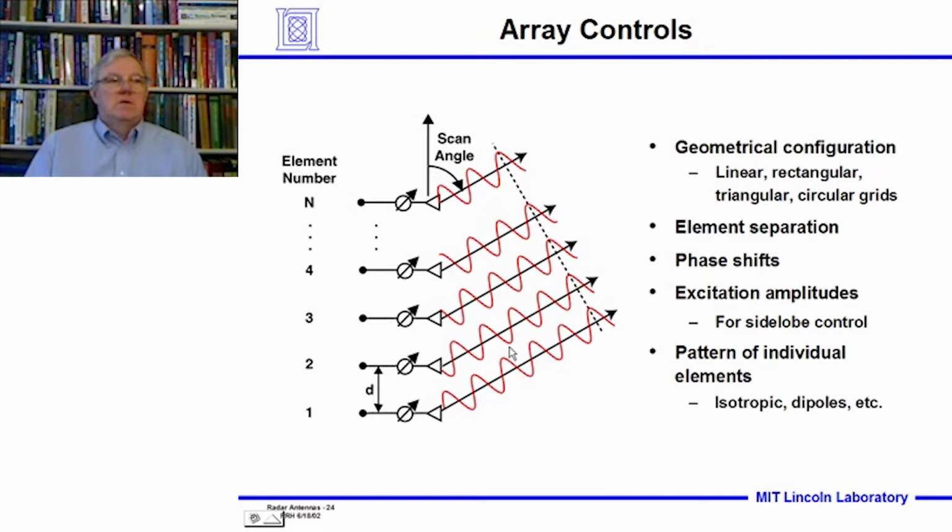Okay? So that's what I need to do, is make those phase adjustments. And as I've said, we now have technology that allows us to make those phase shifts electronically. Just go switch. A few microseconds later, the phase has shifted, and where the antenna is electrically pointing to receive or to transmit has been changed. Change it again, microseconds, it's pointing in another direction. Okay? So we have lots of different